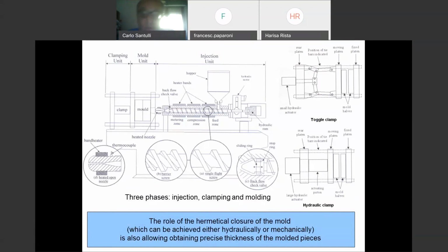Otherwise, they wouldn't flow. Of course, the frequency of rotation is important, because you would think that I can make them rotate at a very high frequency, but in the end, if you rotate them at a very high frequency, you get a lot of losses. In practical terms, you get a lot of deformation, which results in you not being able to fill the mold because your plastic would go everywhere apart from the mold. So you would need to tailor your frequency of rotation to the requirement to fill the mold. And it depends on the type of piece you want to create.